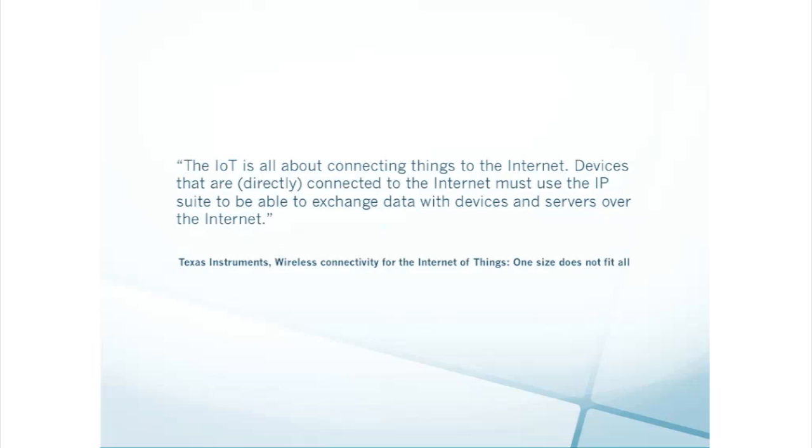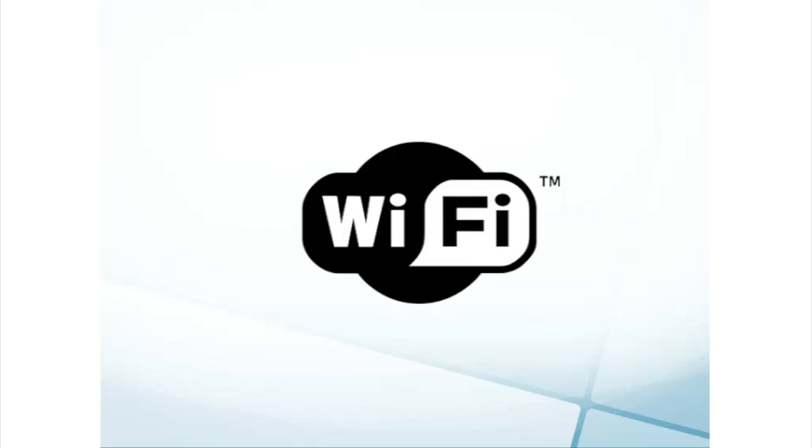As we've discussed, IoT devices need to communicate with each other and to the Internet. So let's take a look at the wireless option and how it might impact our bill of materials and our cost per node. So Internet connectivity means Wi-Fi, right? It seems pretty logical. It seems like the natural choice. And technically, it's easier to get nodes talking to each other and to the web if we do this. I mean, we're dealing with proxies, routers, switches, stateless protocols. All this requires a proper IP stack. But really, the cost of Wi-Fi, putting it everywhere on every node, is going to add up.